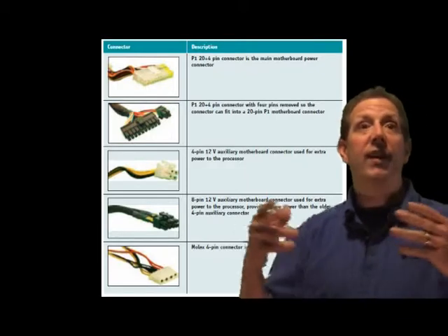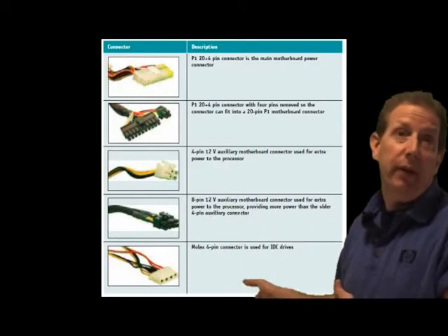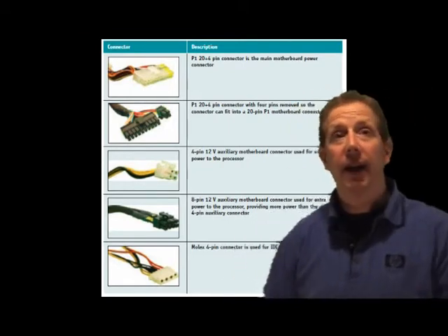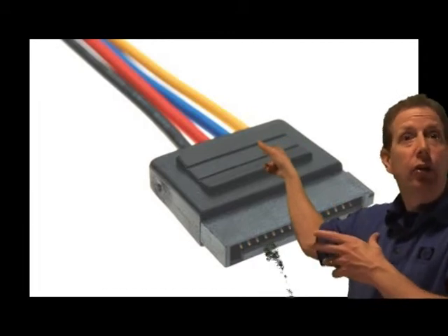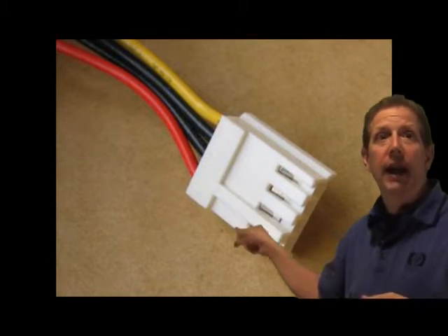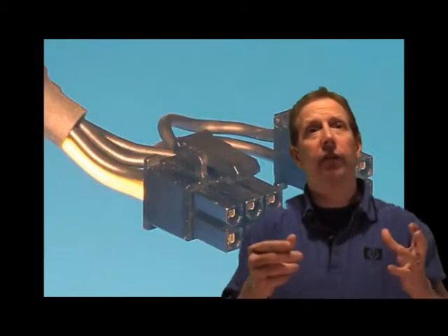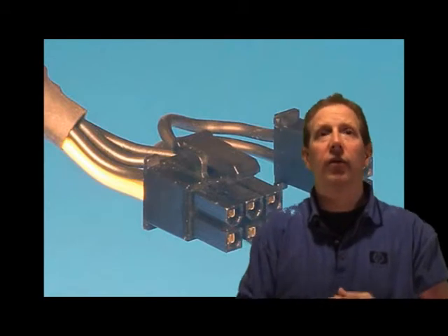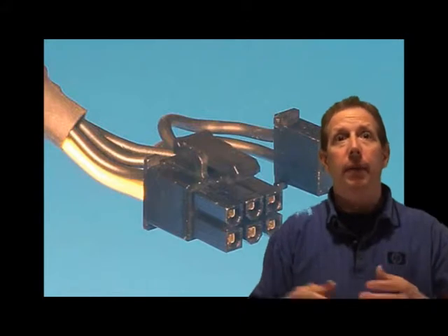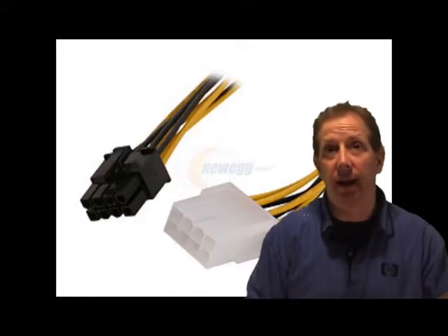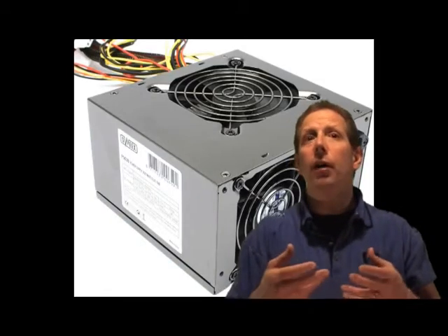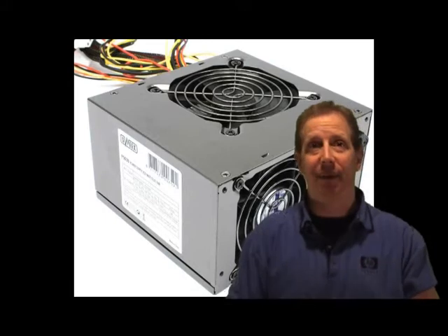Next, the one that is fading out of existence due to the growing popularity of SATA is the Molex 4-pin connector. It's used for IDE drives. Next, we'd like to turn your attention to the SATA connector, used for SATA drives. Next, the floppy drive connector, hardly used anymore. And then next, the 6-pin plus 2-pin, plus 12-volt connectors used on high-end video cards for PCI x16 slots and so on. PCI Express version 1 also uses a 6-pin connector, and PCI Express version 2 uses the 8-pin connector. To get the 8-pin connector, combine both the 6-pin and the 2-pin connector.